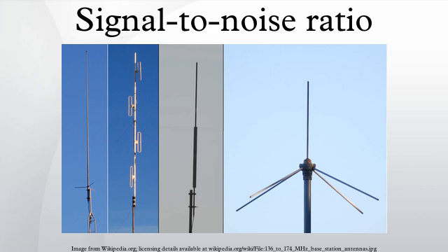Alternative definition: an alternative definition of SNR is as the reciprocal of the coefficient of variation, that is, the ratio of mean to standard deviation of a signal or measurement. Where the numerator is the signal mean or expected value and the denominator is the standard deviation of the noise, or an estimate thereof. Notice that such an alternative definition is only useful for variables that are always non-negative. Thus it is commonly used in image processing, where the SNR of an image is usually calculated as the ratio of the mean pixel value to the standard deviation of the pixel values over a given neighborhood.